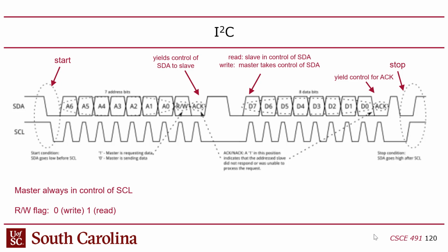But I don't even know how that works exactly. I think it's in the protocol guide somewhere. But if we assume there's no transaction, you start it up by dropping the data line while the clock is high. And then at that point, the master sets up the data and pulses the clock. Set up the next bit, pulse the clock. Set up the next bit, pulse the clock.